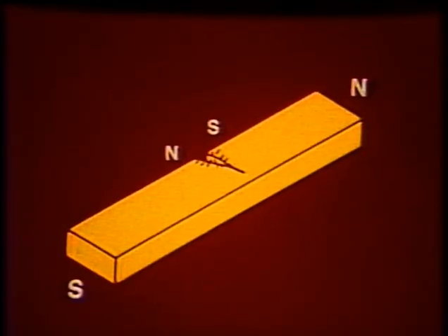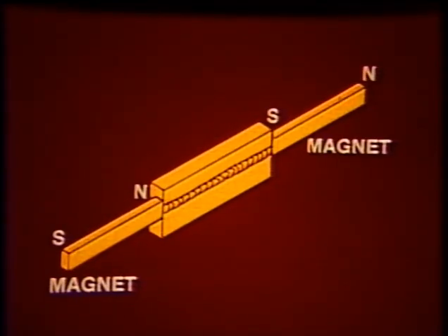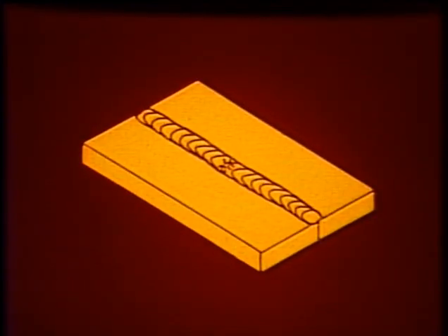Using this principle, if a part is magnetized by placing it in a strong magnetic field or by passing current through it, the part will behave like the bar magnet. If a flaw exists on the surface or slightly beneath, it too will develop magnetic poles and attract particles roughly in the shape of the flaw, creating an indication that a discontinuity exists at that place.